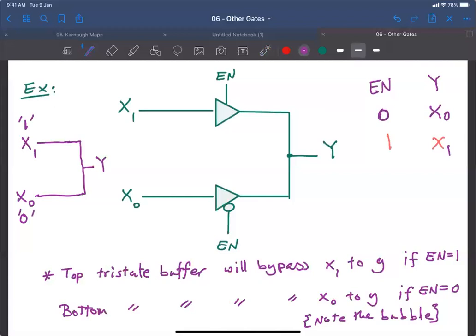The signals will fight over the line. One is saying no, it's logic 1, and the other is saying no, it's logic 0. If you have a system like this, we can imagine that we have a resistance here, which is 0, because it's just a wire. What is the current passing through this resistance?